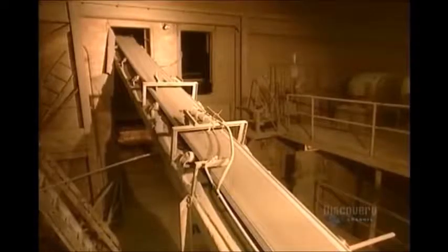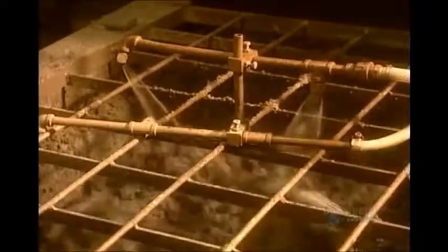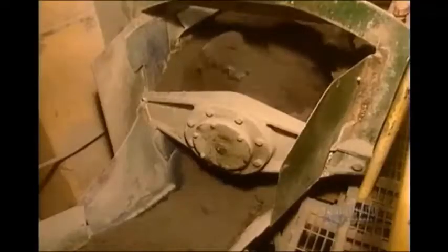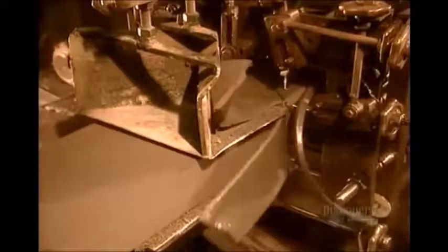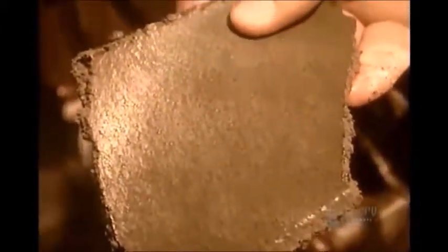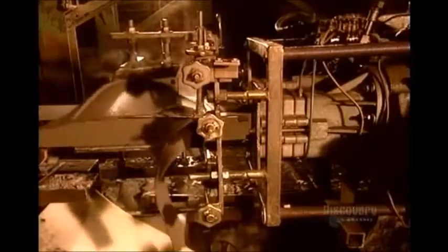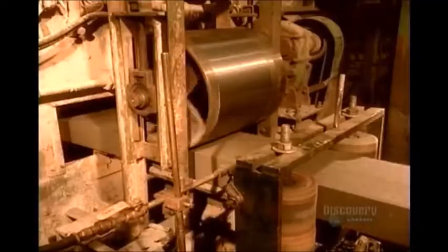The powder goes to the pug mill, which mixes it with water. This makes a thick paste that will next go through the extrusion machine. The extruder forces the paste through a rectangular opening to form one long continuous piece called a slug. At the same time, it shaves off the crustier top layer to expose what will become the face of the brick. If this gray shale mixture is fired as is, it'll naturally produce a red brick.